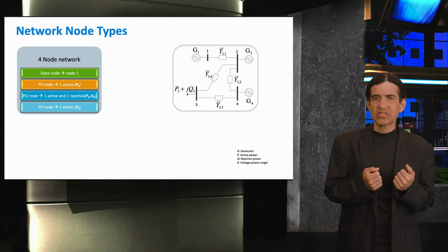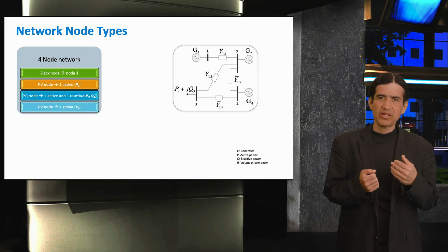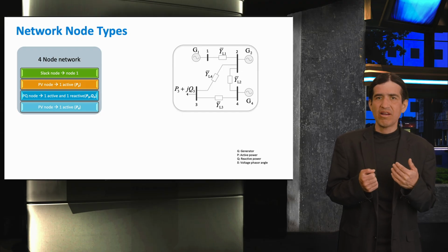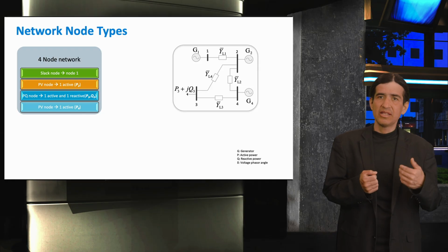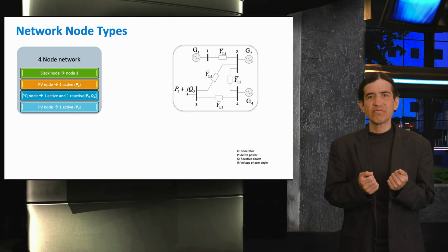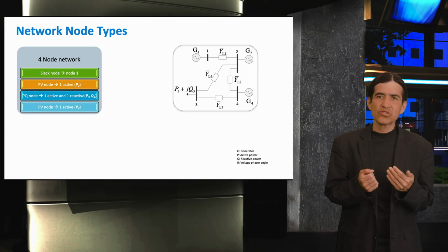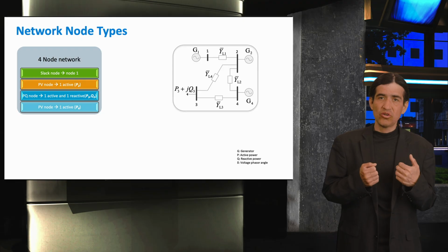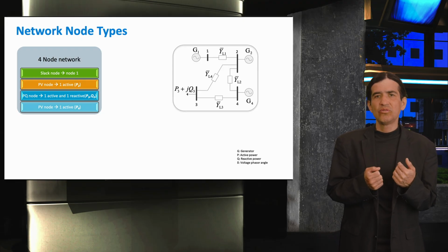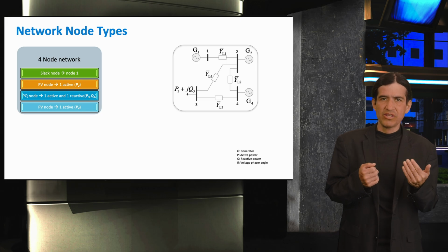Let's now illustrate the structuring of equations with a simple example concerning a small-sized synthetic power system having a 4-node transmission network that interconnects 3 generators and 1 load. For instance, bus 1 can be assumed as a slack bus or slack node. So generator G1 is set to define the reference voltage phasor of the system.